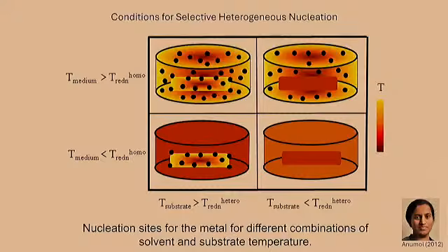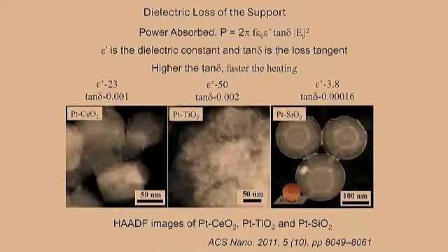Okay, so what does microwave heating depend upon? It depends upon the dielectric loss of the material that we talked about, right? Silica has a very low dielectric loss, and that's why the cup doesn't get heated. Water has a high dielectric constant, high dielectric loss, and therefore our food gets heated much faster, right? So that's what happens in a microwave.